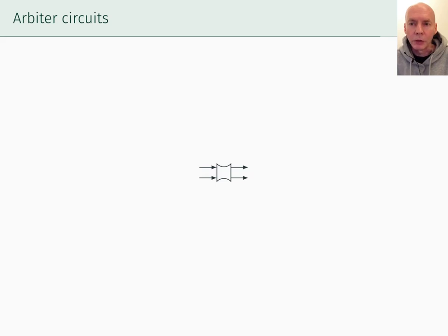I'm no physicist, but what I can gather about the physics of the situation is that the closer together in time the input requests arrive, the longer it will take the arbiter to come to a decision. But even if the requests are perfectly simultaneous, the arbiter will come to a decision in some finite, albeit unbounded time, because it will be resolved by thermal noise.